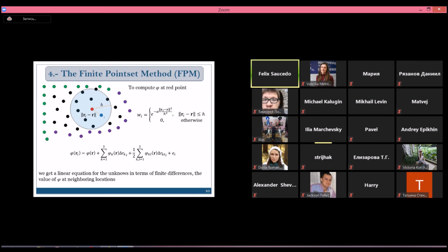Yes, this is a geometrical problem. As you say, we can have a zone with a coarse number of particles, but we also have some zones with a fine number of particles. So you can always delete particles, for example, with an interpolation between the properties, so you assure that the particles you eliminate from the domain are not lost. You consider this information in the closer neighbors. And in the opposite case, when you have a hole in the domain, you can always add new particles with geometrical algorithms, for example, a triangulation algorithm, and you also interpolate the new particle's information with the information of the neighbors.